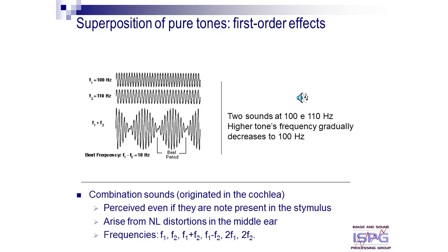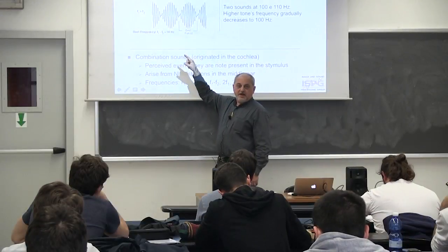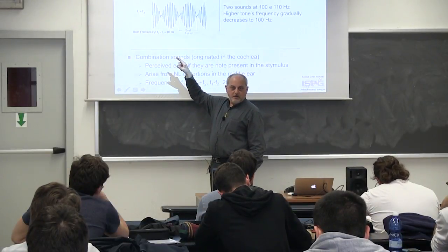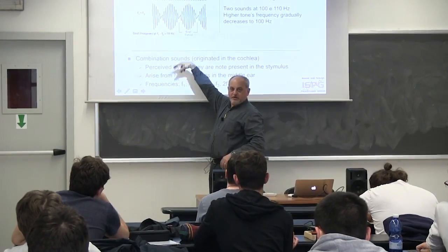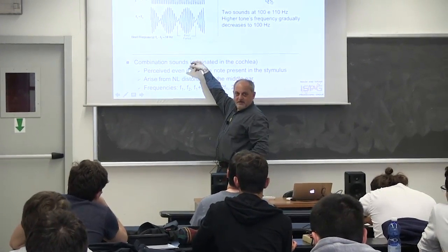This shows the combination of the two cosinusoids, and the result of that combination is this particular formula showed up there. As you see, the sinusoid is at 5 hertz, but the magnitude, because of the reversal, will be at 10 hertz. Does that make sense?